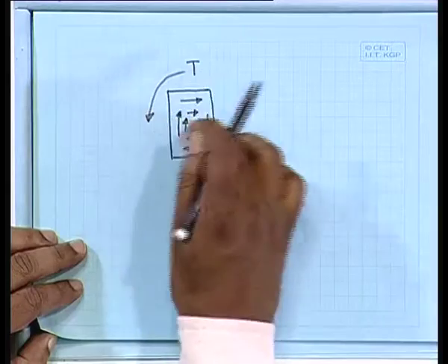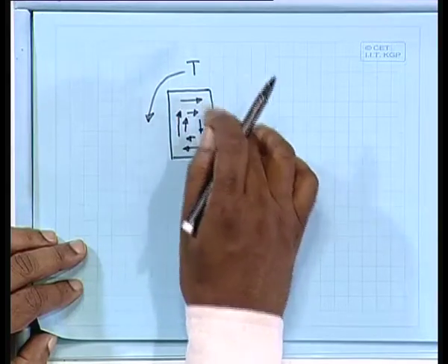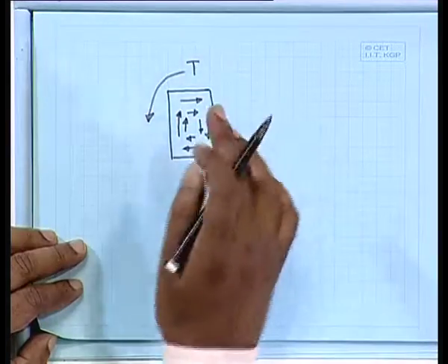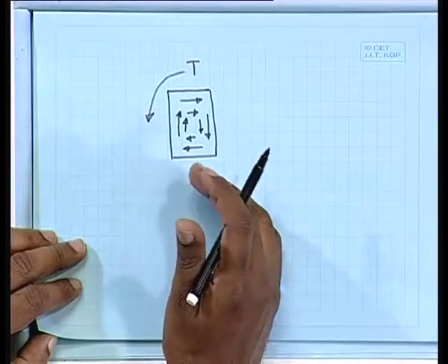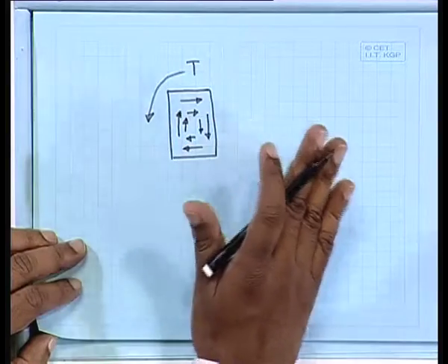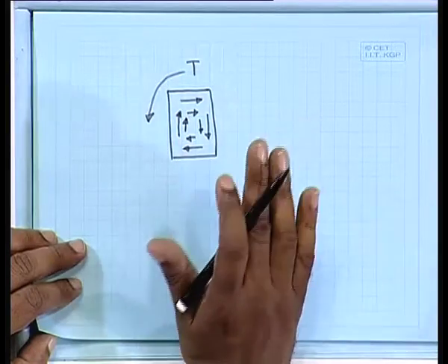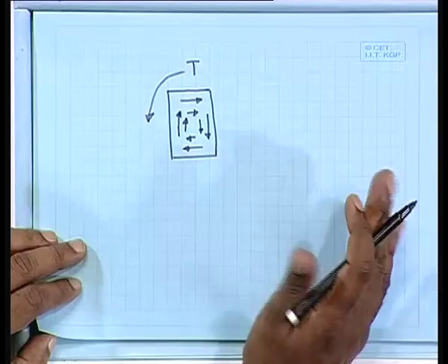That is the philosophy here, how we are taking care of the torsion. Due to this torsion, shear stress is developed on the surface, and accordingly you have to provide sufficient reinforcement, so that we can resist shear, cracking can be avoided, with the longitudinal reinforcement and your stirrup reinforcement.